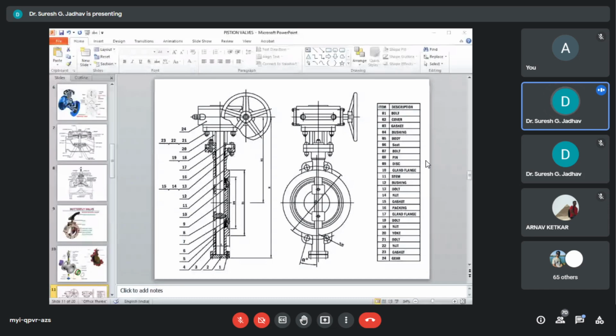Tight shut-off is troublesome since particles jam between the closing surfaces. Further, the valve must be strong to lift up the disc against the weight of the solids in the hopper. The advantage of these valves is that the wear resistant elastomer has a longer life expectancy than the conventional metallic seat.